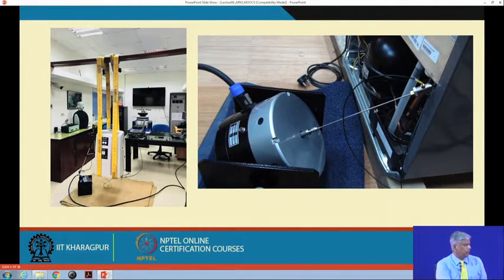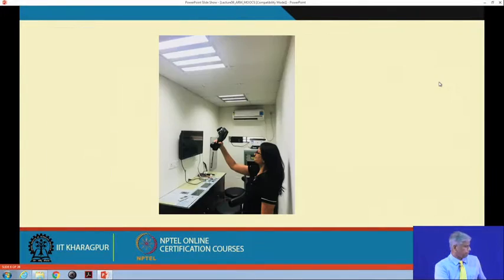This is a model testing which is being done on a refrigerator, and you can see this is the electromagnetic exciter, and this end this is the impedance head, wherein I can simultaneously measure the driving point FRF by measuring the acceleration and the force at input to the system. And this is inclined because then I can give in vibration at 2 or 3 different directions.